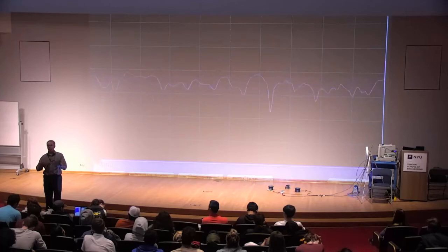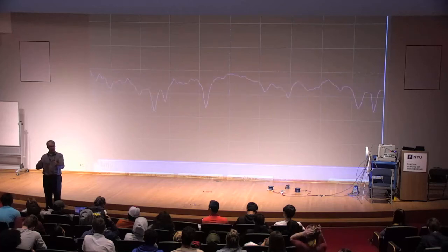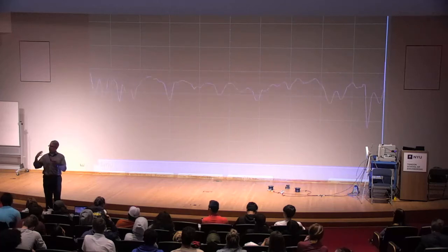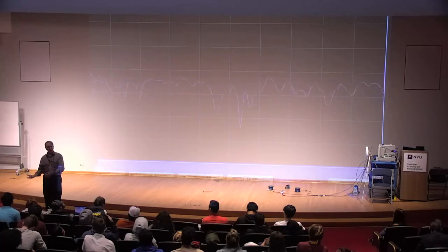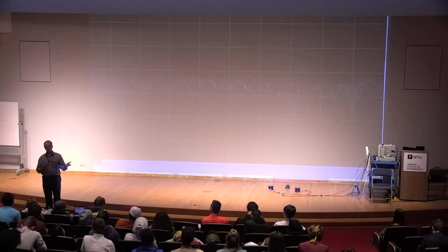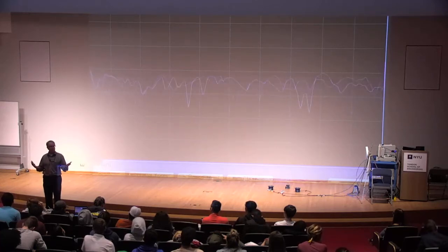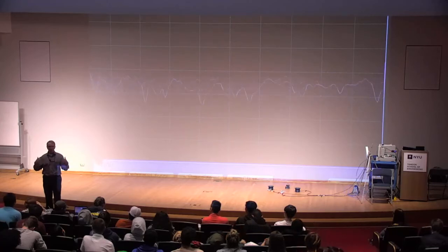As time went on, they moved to 2G, 2nd generation cellular. That's when they made the switch to digital, and we've been digital all along. Now, what do I mean by digital? Officially for voice, we're taking your voice and converting it from analog to a digital representation. That's what's transmitted. It's essentially ones and zeros. And then at the back end, I take those digital bits, ones and zeros, and I convert them back to analog. Because unfortunately, we still live in an analog world.